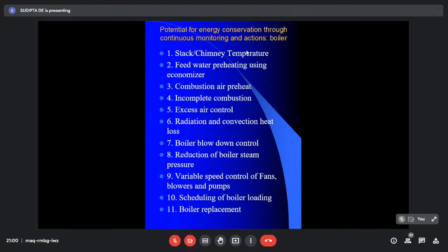But it simultaneously decreases the flue gas temperature inside the boiler, as excess air is always supplied from the local atmosphere at a lower temperature than the inside temperature of the boiler.